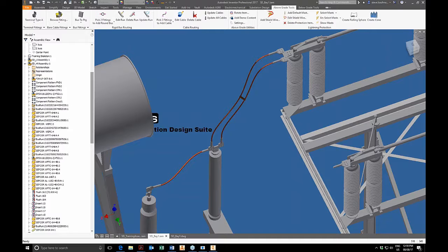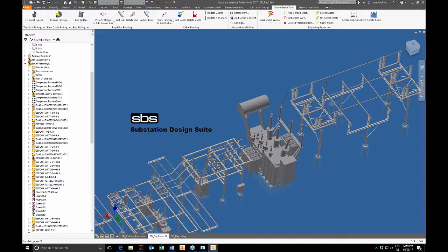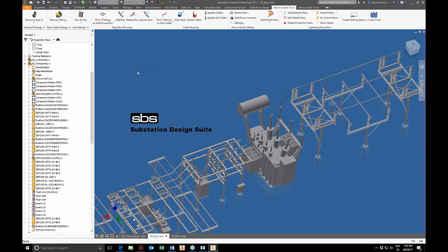I know this is from David. I know this is a function of Inventor, but there's no issues creating a 3D PDF from the model, correct? Correct. The only issue is in the older versions of Inventor, 2017 and such. Oh, it just started in 2017. So 2018 of Inventor does the 3D PDF quite well. 2017 didn't do it as well. 2016 Inventor does not do it. So you need a third party software to convert your 3D model to 3D PDF if you're at 2016 or previous. But 2017, 2018 all have 3D PDF direct. Works quite well. We've used it a few times.